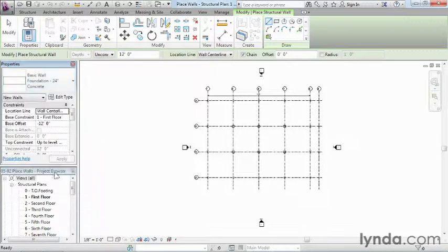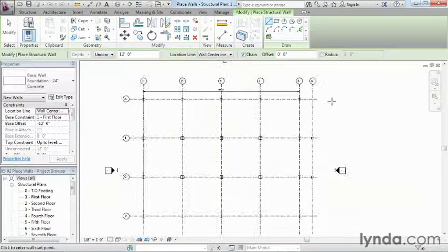and then just select foundation 24-inch concrete off of your list. Next, we're going to move over here, zoom in just a little bit, and what we're going to do is we're going to place a foundation wall going from A-1 over and down, back over again, and then back up in order to finish it off.